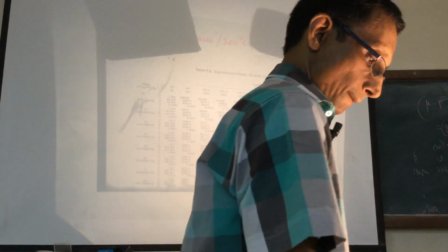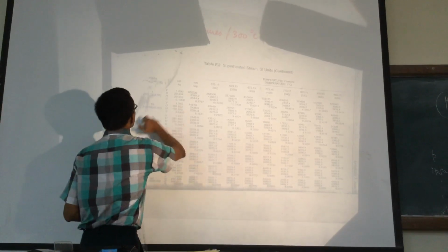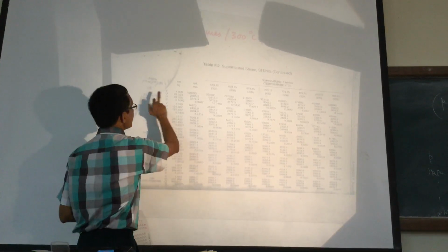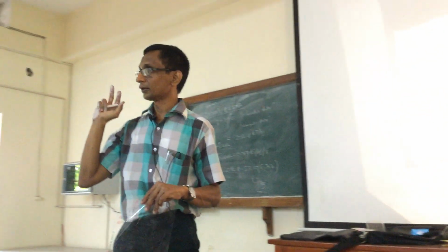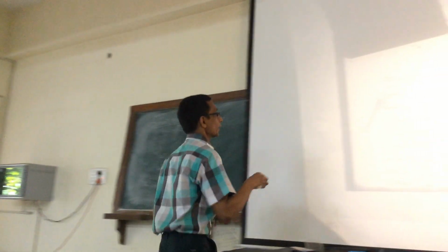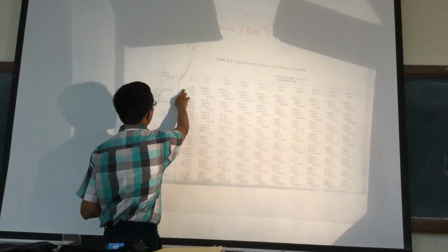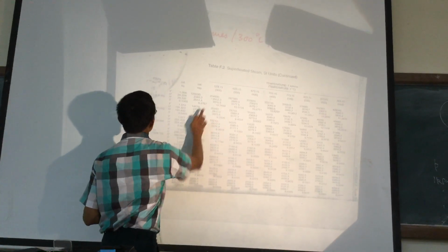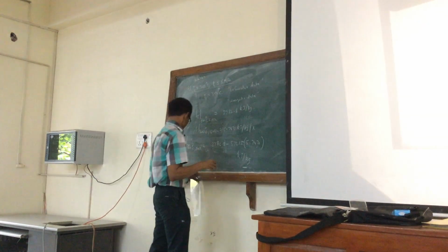Okay, the lowest pressure is 1 kilopascal, right? So now at 300, that is very important. Temperature you have to keep in mind. Temperature is always 300. Since ideal gas refers to the low pressure behavior, I am calculating here. I write down the H here at 573.15. H is 3076.8, right? So 1 kilopascal.